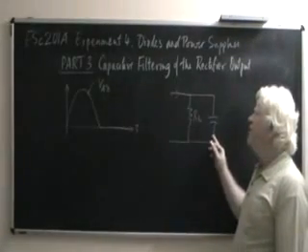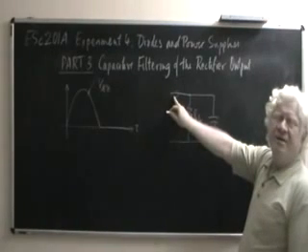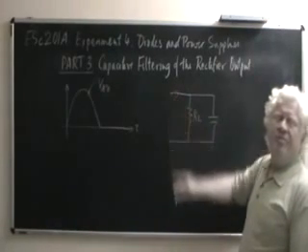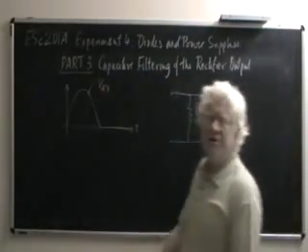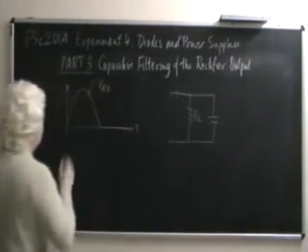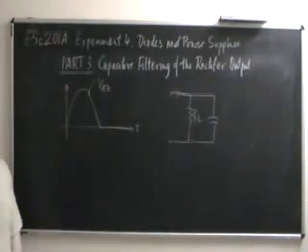provided the capacitor voltage is less than the rectifier's output. This will happen, for example, if the initial capacitor voltage was 0. Let us suppose that at this point of time the capacitor voltage was 0.